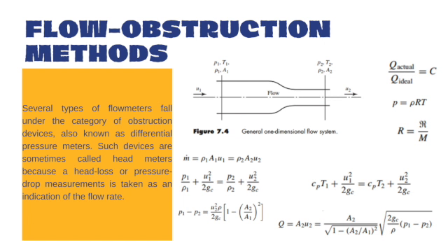And we see on the right side that the volumetric flow rate may be written as Q equals the way it's expressed there. And we see here in the channel shown above, this could be used for flow measurement by simply measuring the pressure drop and calculating the flow.